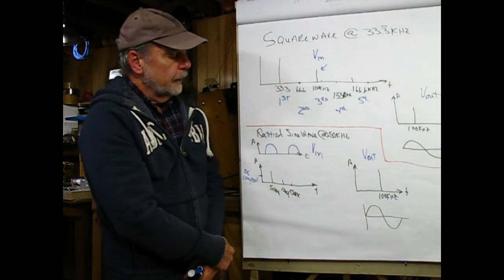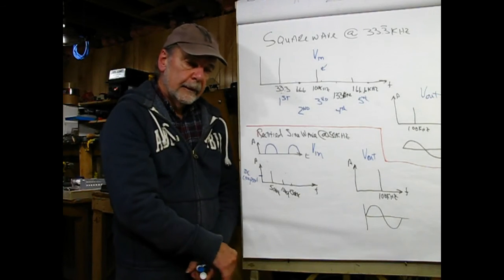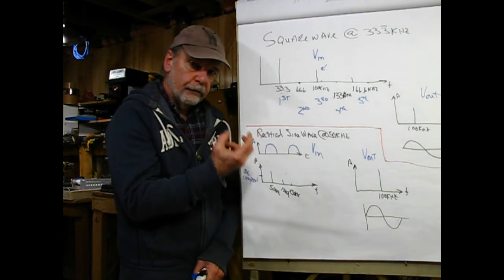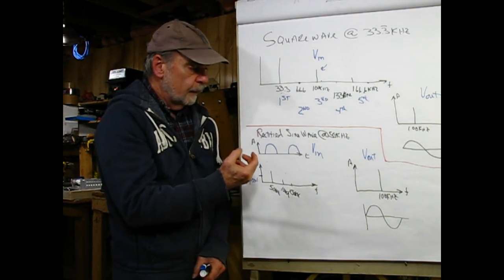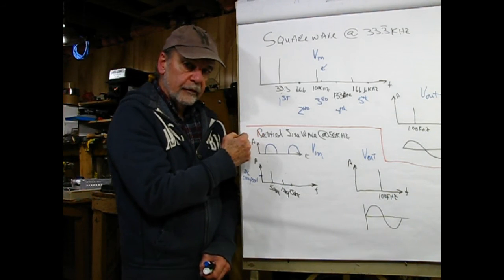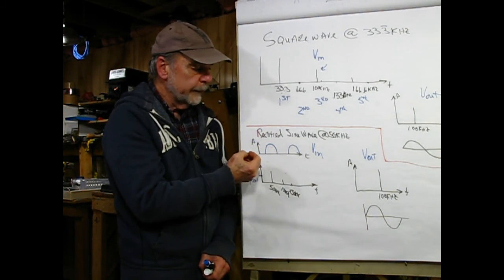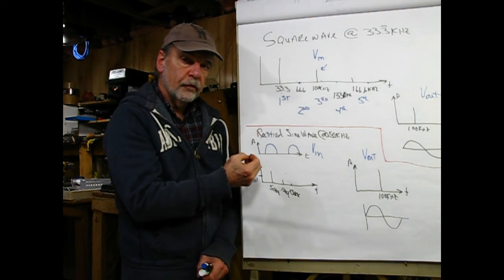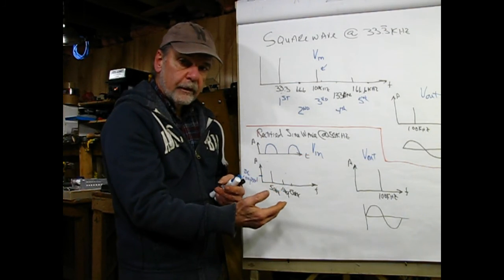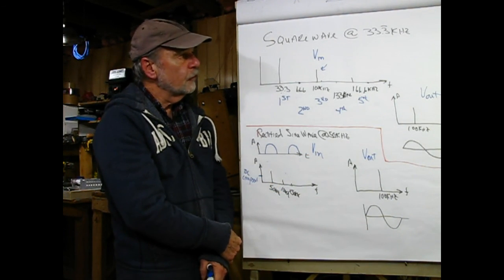So in conclusion, you can make a frequency multiplier very easily. It's just tuning the circuit to the frequency you want and then feeding into it something that's a sub-frequency of it that's distorted. It has a harmonic component at the frequency of interest. And then that tuned circuit simply eliminates every other thing, and we get out what we want to get out, which in the case of this example would be 100 kilohertz.